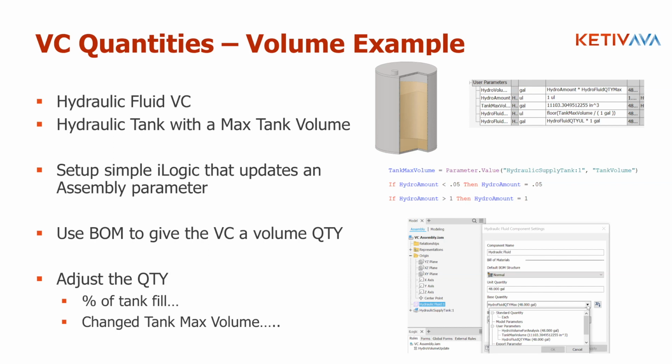I mean, I would think that if you wanted to have a virtual component-esque part, no geometry, if you just wanted to maintain property information for the material, you could just create a blank part and then be able to reference that multiple times. Yes, absolutely. And there's nothing wrong with doing that. Like I said, virtual components are there for the convenience of your workflow. They're not the only way to solve the problem of having a line item when you don't need geometry. Empty parts work just as well for that.